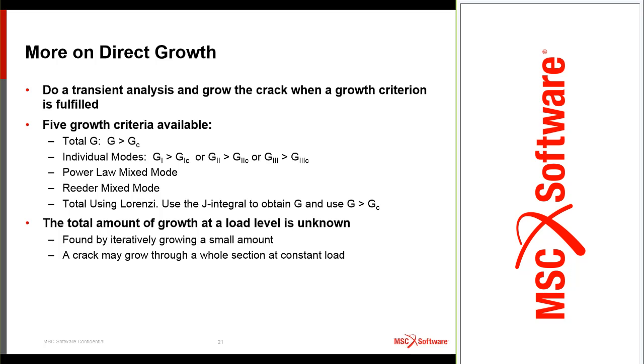If you specify too small an amount, you need a very fine mesh to resolve that small amount, and you may get into a large number of iterations. And if you specify too large an amount, you may overshoot the actual solution.